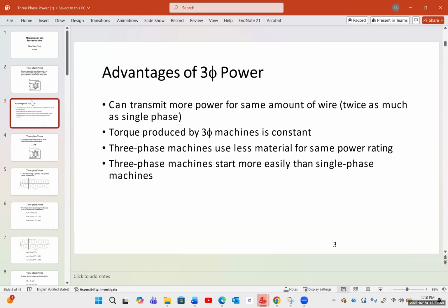And the other problem is you're going to put much more wires, the transformers, the transmission lines, the insulations. It's going to get very complicated. The distance between the wires, when you double the amount of wires, would be halved, and therefore you're going to induce a lot of reactive loss on the system. It acts like a big coil. But there are other reasons for that as well.